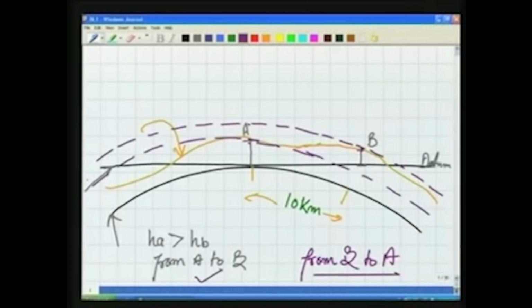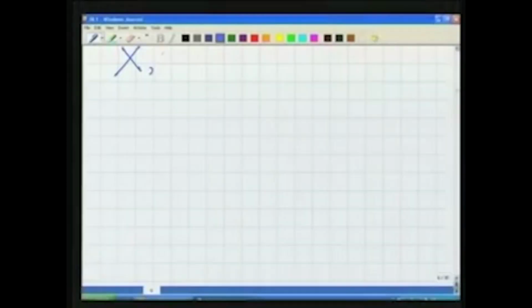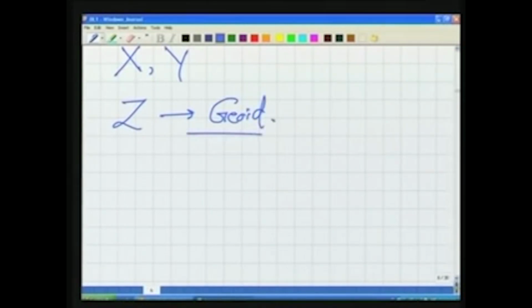What is the case here? So, what do we mean by this? We mean by this is, if we are taking the horizontal plane for measuring elevations, our elevations will be wrong. It might happen that we are giving the elevation to a point, as here in this case A, more than to a point B, despite the water flowing from B to A. So, we must always measure the elevations from the geoid, not from the horizontal plane. It says that in all our engineering surveys, we can consider our earth flat for x and y, but for Z we must measure from the geoid. So, this is an important concept, we should keep that in mind. This is what we had discussed last time. These are important concepts, that is why I wanted to repeat these.